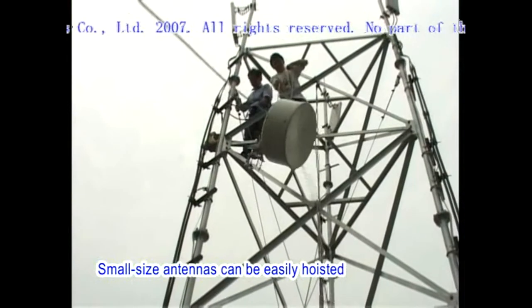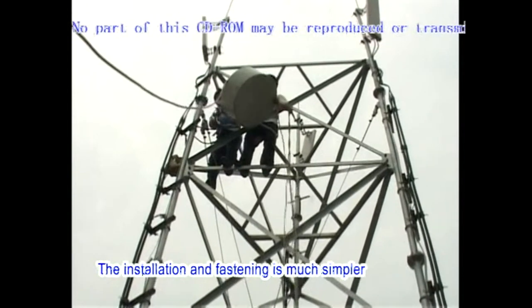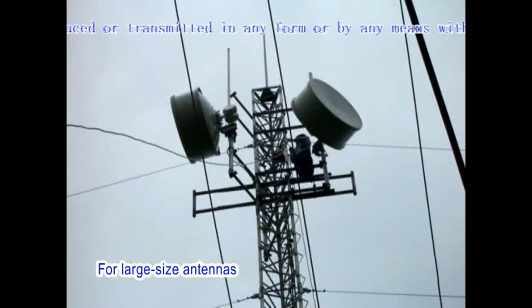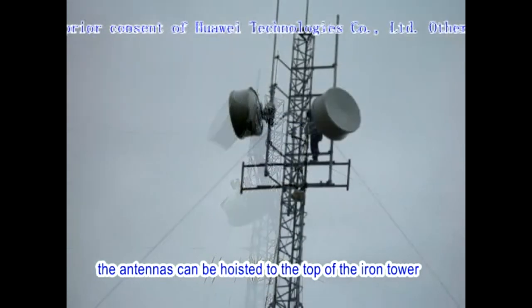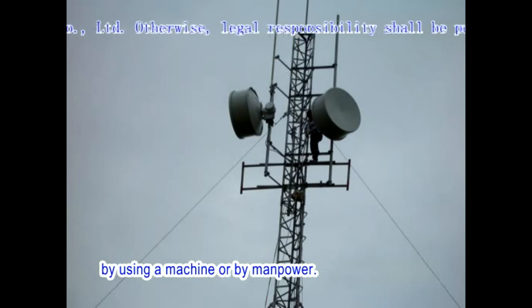Small size antennas can be easily hoisted to the top of the iron tower by 2 persons. The installation and fastening is much simpler. For large size antennas, however, pulleys need to be installed on the top of the iron tower. Then the antennas can be hoisted to the top of the iron tower by using a machine or by manpower.